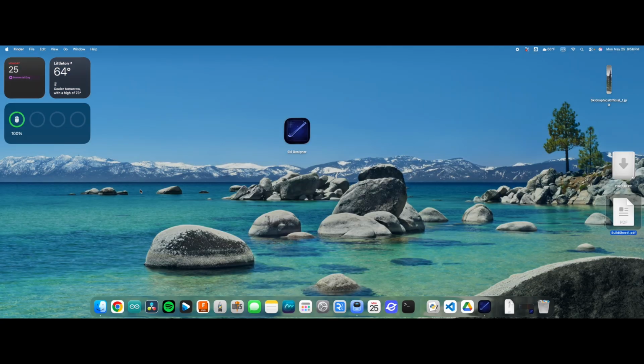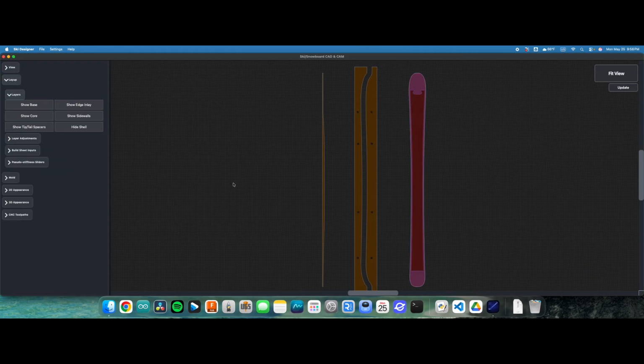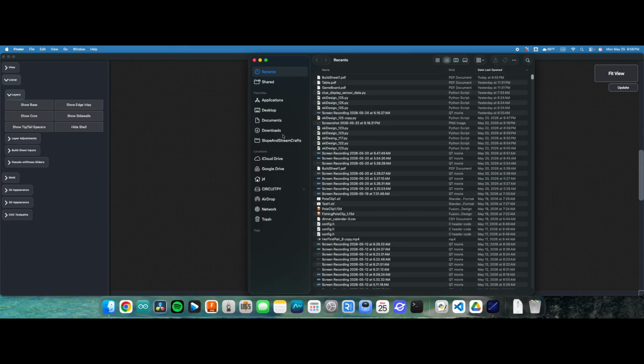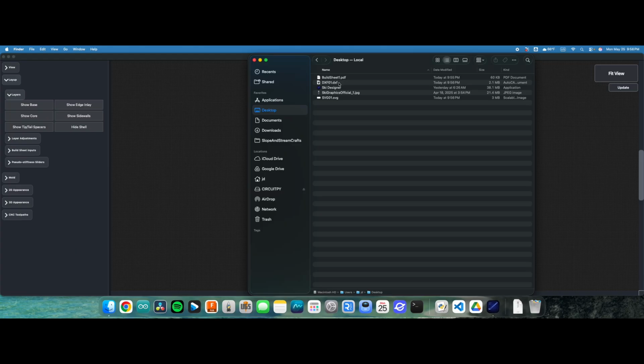Let's check out some of the other types of exports you can do. As a great starting point for any graphic generation, you can export an SVG or DXF and import that into programs like Inkscape, and DXFs are almost more like mechanical based drawings that can go into other types of CNC control software. Let's take a look at what gets exported when you do an SVG though.